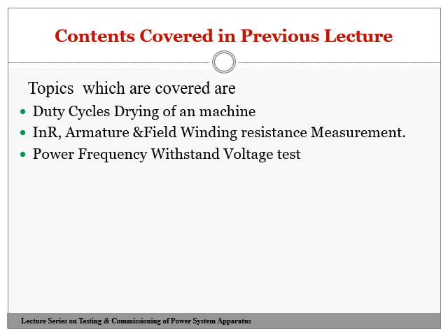Afterwards, we came to know about the need for drying. As you know, electrical machines or electrical equipment have cellulose insulating material, which has the property of absorbing moisture. Once moisture is absorbed by the insulation, deterioration of the insulation takes place, or its insulation resistance decreases. To bring the insulation resistance back to its original value as per the standard, we require drying of an electrical machine, in a similar way that drying of a synchronous machine is done.